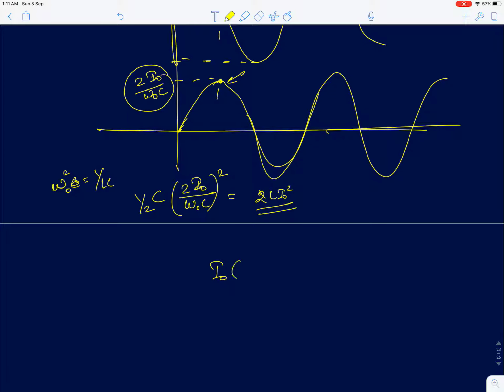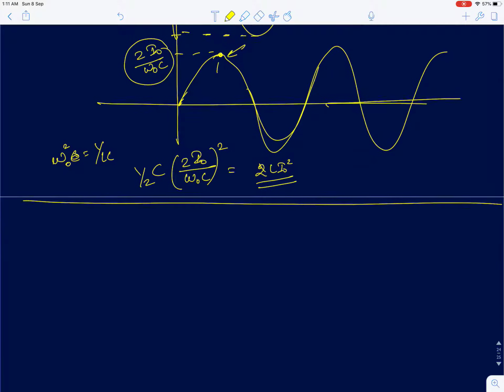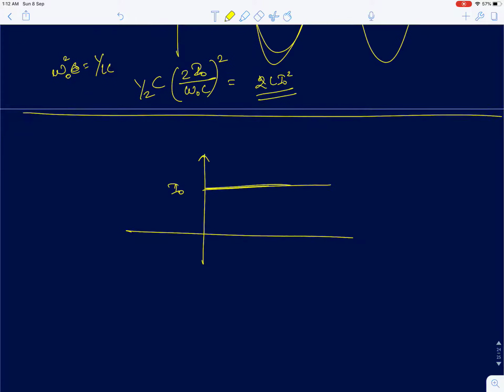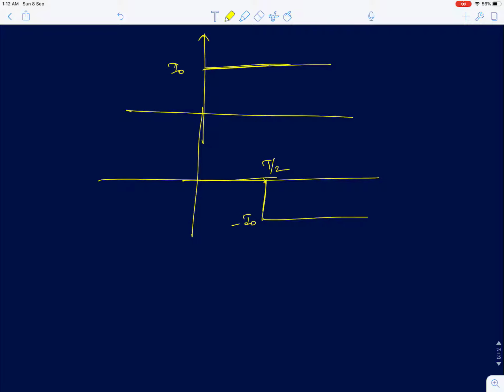And again we can very easily show the inductor current. I can just split it using mathematics. I'm just going to show this same result. The current pulse can be assumed as a superposition of two current pulses, one starting at 0 and another one with a negative sign starting at T by 2, and this is minus I naught.